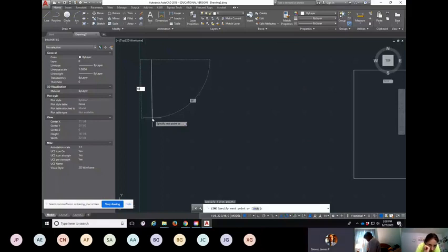That's your direction, your angle. If I want to make sure that line is straight, I'm going to hit the tab button, and I'm going to set 90, and tab back, and it's locked both of them in at 10 and 90, and then hit enter to select your next line.